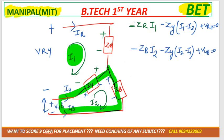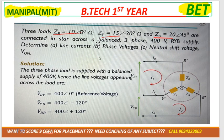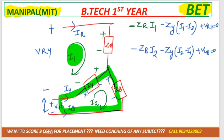After this, as you can see in the question, voltage is given, that is 400 volt. This is the line voltage. So VRY is 400 angle 0, second, as I told you, is minus 120. Third one, you can take as 400 angle minus 240 or plus 120. That's one and the same thing, right? After this, we can substitute the values of VRY and VYB, ZR and ZY. Can we convert it into matrix form?